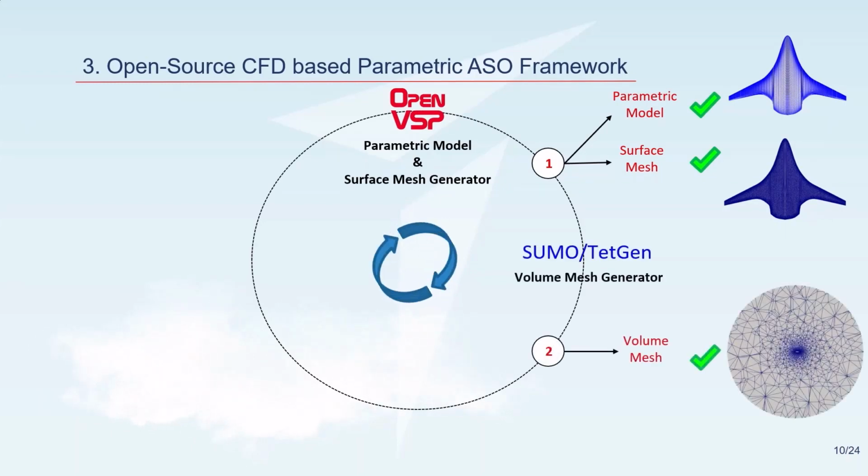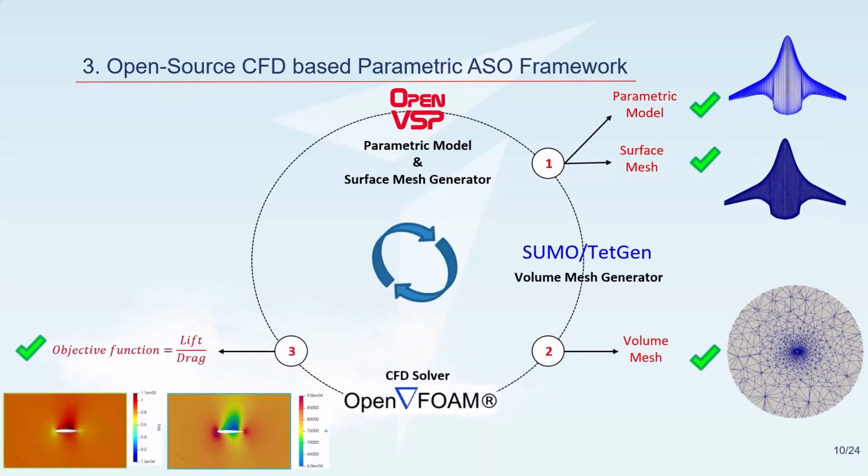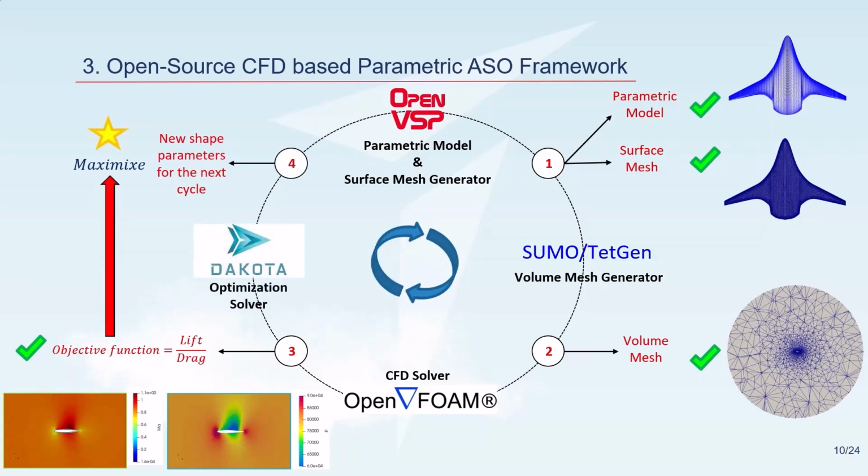The next step is the optimization process. In the optimization study, the lift-drag ratio is set as the objective function. We are using Dakota to maximize the lift-drag ratio of the aircraft.